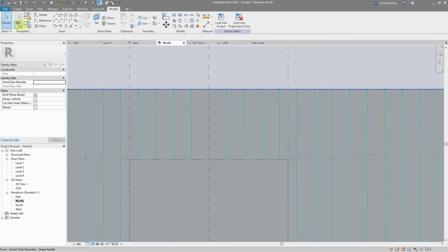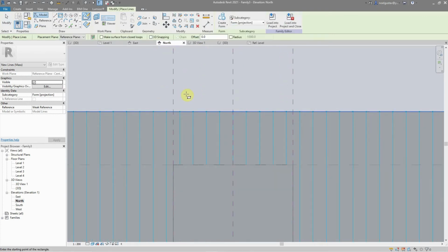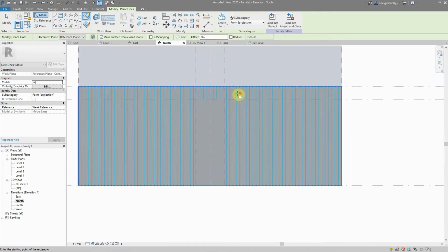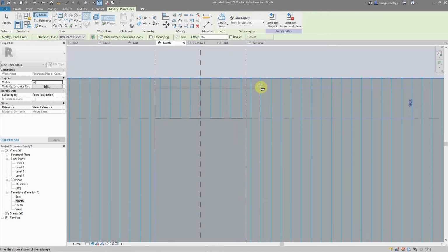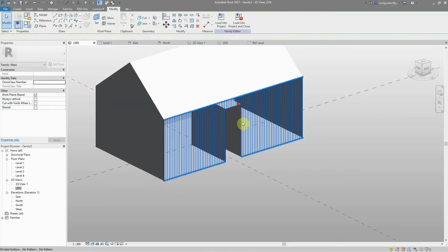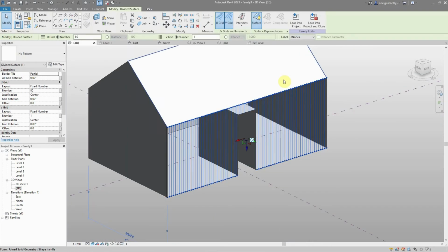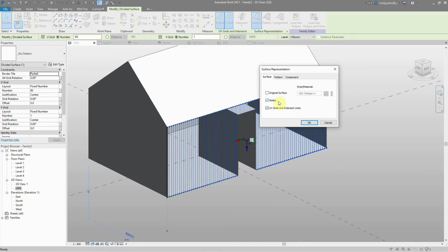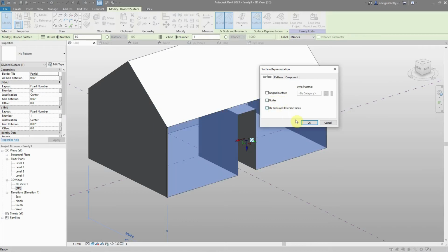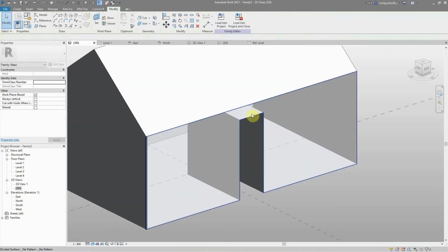And then add a rectangular surface here. But this time, I'm going to make the surface from closed loops so that I can immediately create a new surface here. So after that, I'm going to hit this surface and uncheck nodes, the UV grid and the intersect line so that I can have a model as plain as possible.